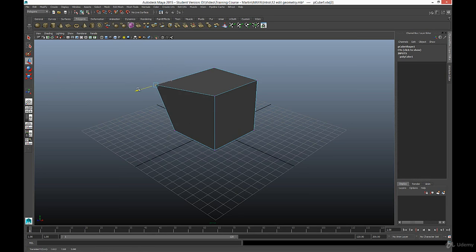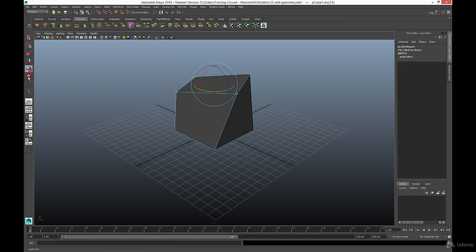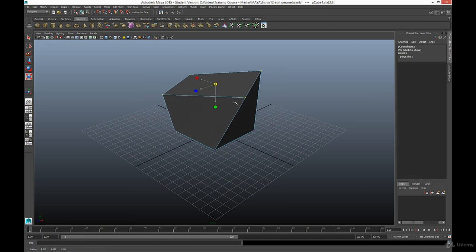So by selecting that point, I can drag along each axis and begin to sculpt and shape the points inside of the scene. I can also make a multiple selection of the vertices and then use other options such as rotate, and then rotate that selection. I can also scale that selection. Nice and simple. And that's how we can select the vertices, and then we can use our transform tools to actually maneuver and place those points around in the space.